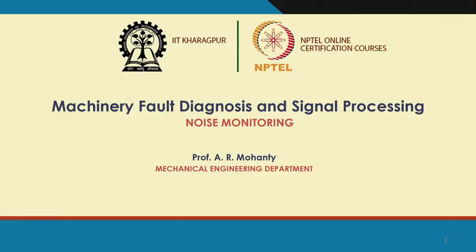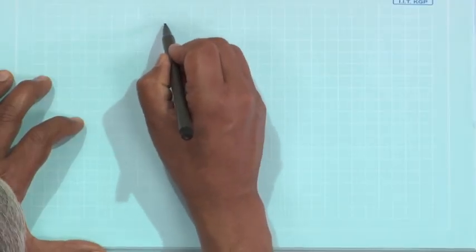In the previous lecture, we had an introduction to noise and sound, and in particular regarding the sound pressure level in decibels, and then how to add decibels, and then what happens for a spherical source or a point source in 3 dimensions: how the SPL reduces by 6 decibels for every doubling of the distance. Okay. And then we did discuss certain conditions as to the fields of noise: